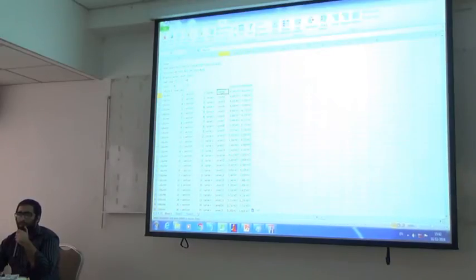Now for level 1, this is the maximum shear force, and this is the minimum shear force. Level 1 section cut, this is the story section cut. Right, for level 2, the maximum and minimum force is already here. Right, for level 3, the force is here. Similarly, for every wall, there is a section cut and then you get the force for every wall over here also.